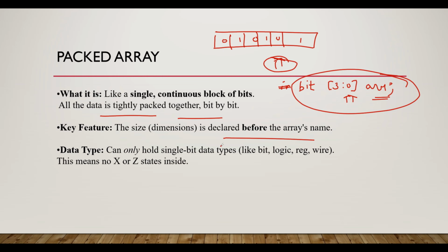Another point you have to take care of is that packed arrays are able to hold only single-bit data types. What I mean is, there are many single-bit data types which we have learned in our data types video: bit, logic, reg, wire. These are all single-bit data types, so packed arrays are allowed for these data types only.